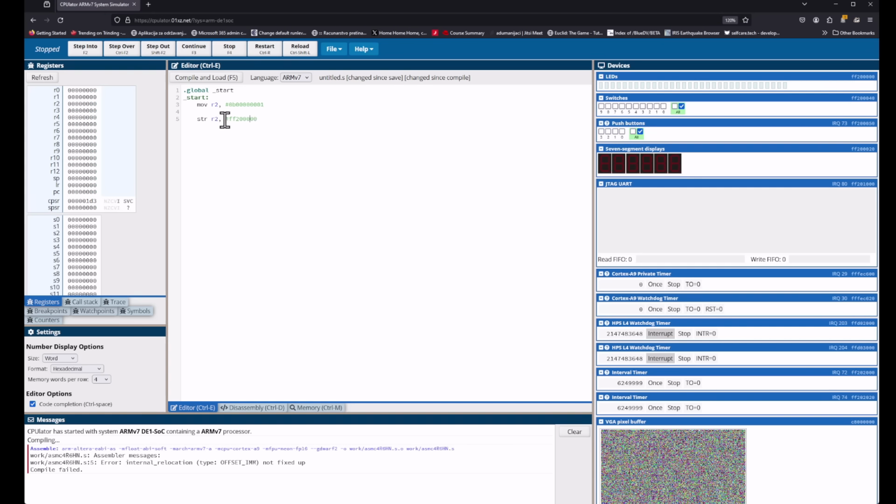So how do I solve this? Usually, the simplest way is to define something called a data block. I'm going to say this is the data block, and I'm going to call it LED, and then I'm going to put the data here. This is the value that I was trying to deal with, and I'm also going to prefix it with 0xFF. So this is the hexadecimal value.